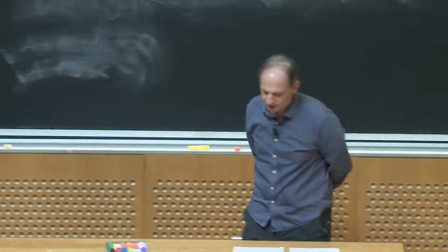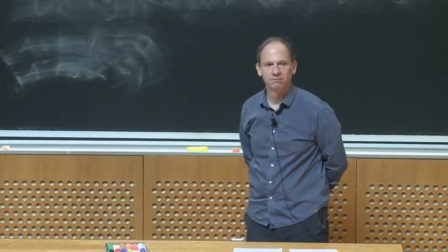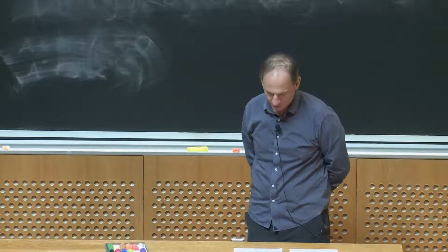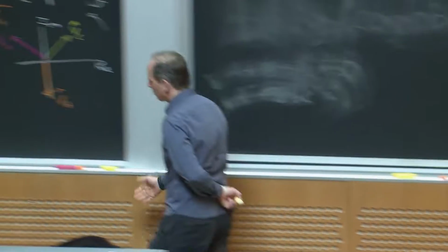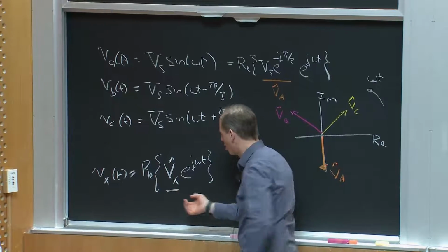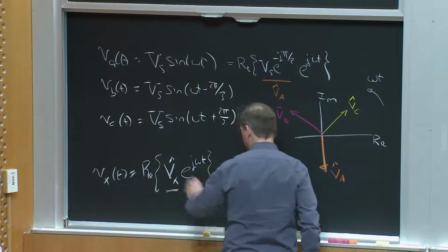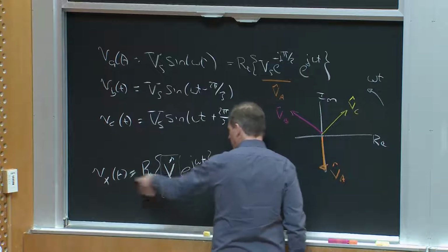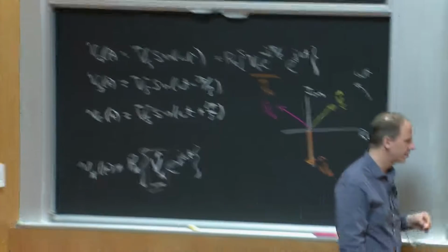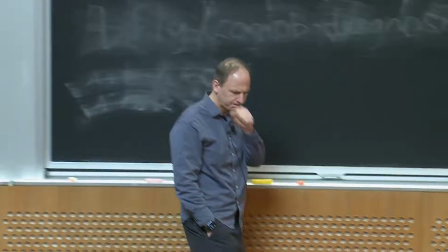Okay, so I can create a set of 3 phases that way and represent them with a phasor. Okay, so I can talk only about this component if I desire, understanding that the instantaneous waveform is rotated and projected to get the instantaneous time domain value.